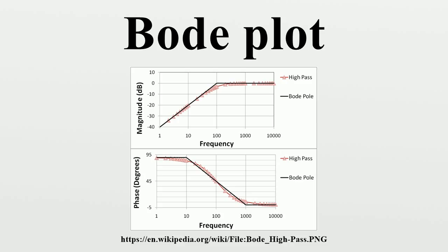The straight-line phase plot is horizontal because the 45 degrees per decade drop of the pole is arrested by the overlapping 45 degrees per decade rise of the zero in the limited range of frequencies where both are active contributors to the phase. Example with pole and zero.